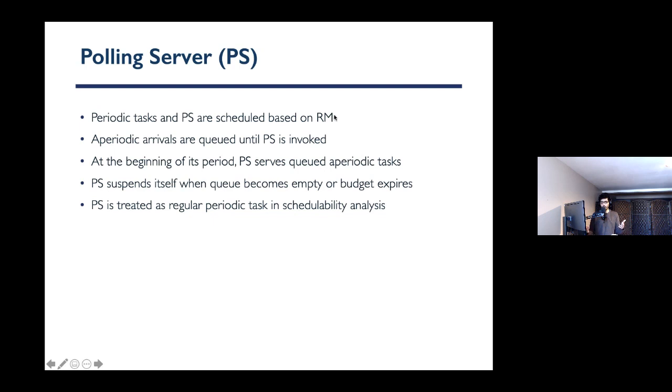By playing with the period of PS, we can set the priority that we give to aperiodic tasks, because PS represents all those aperiodic tasks. If we give PS a long period, we are giving aperiodic tasks low priority. If we give PS a short period, we give high priority to aperiodic tasks. And anything in between, you can just play with it.